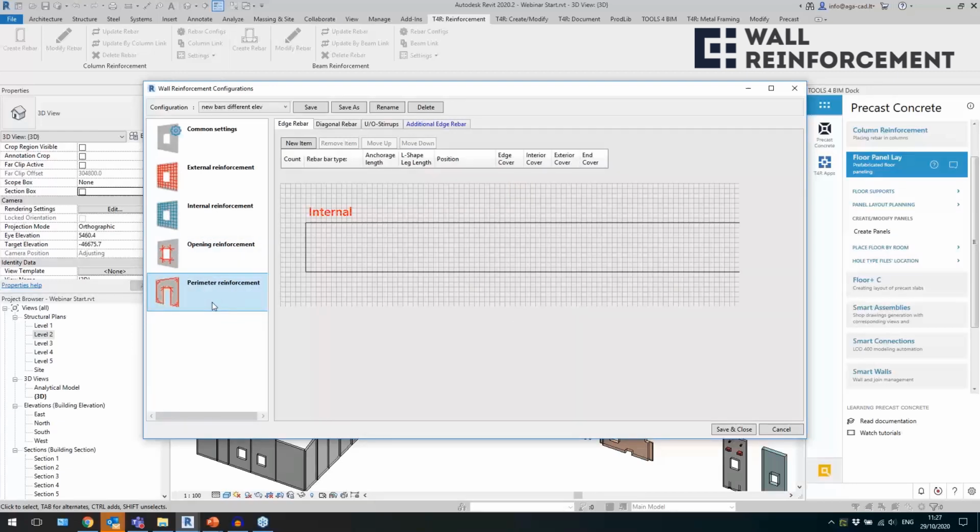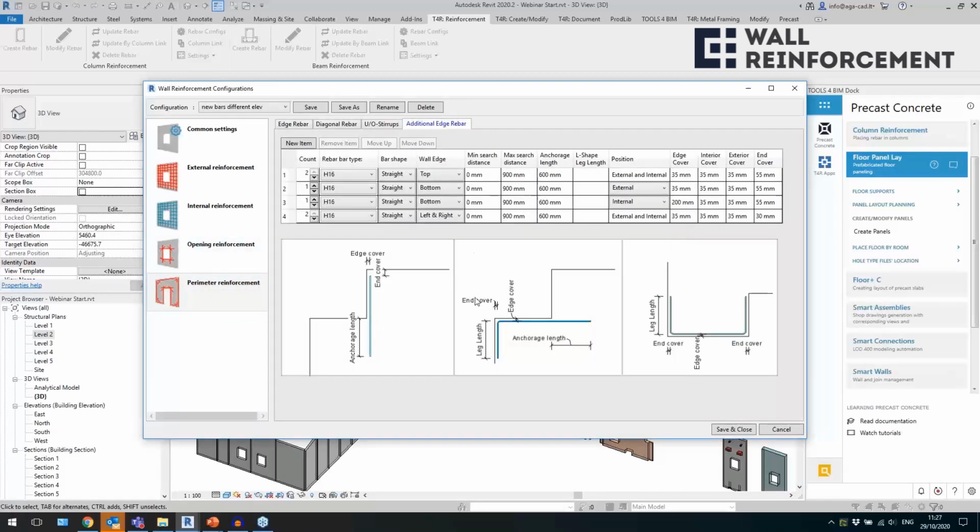to make layout. And then most important probably update was this one, that you can create a straight or L-shape or U-shape bars of a selected size. Depends how many of these do you want to select in one wall layer. Then from which on which side of the wall.